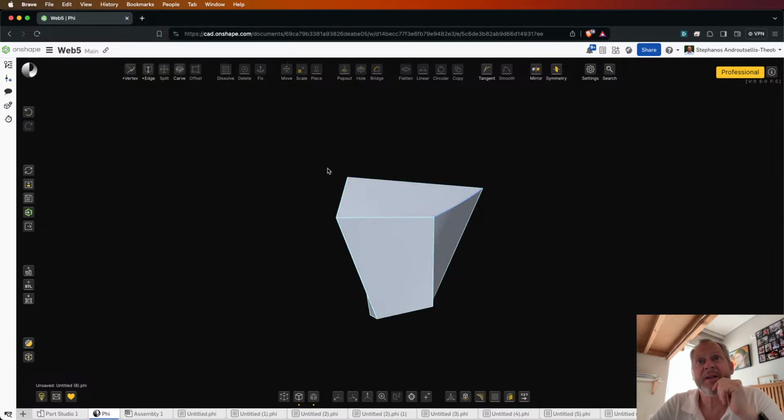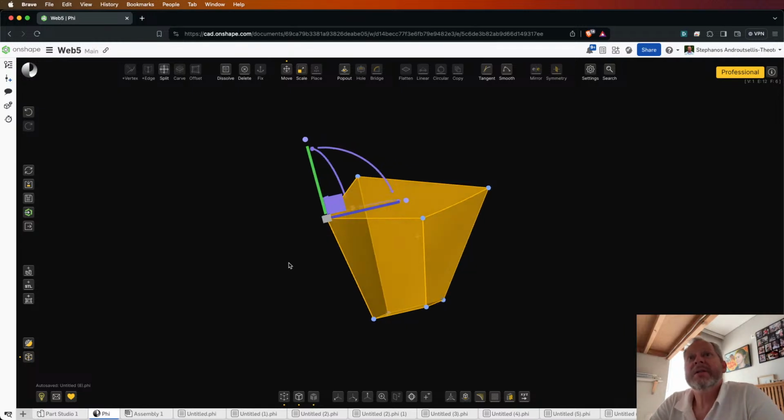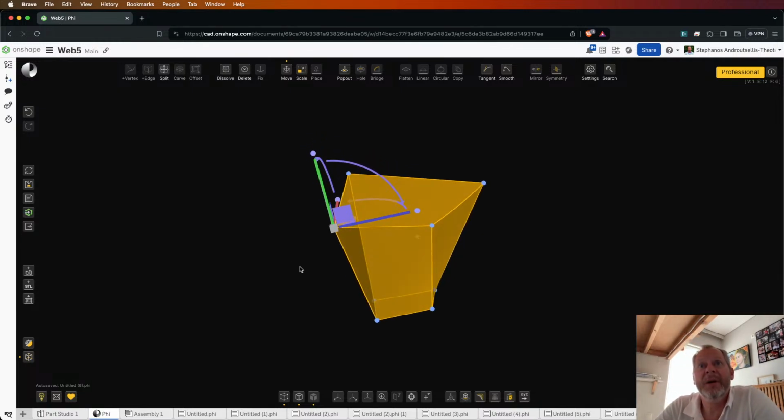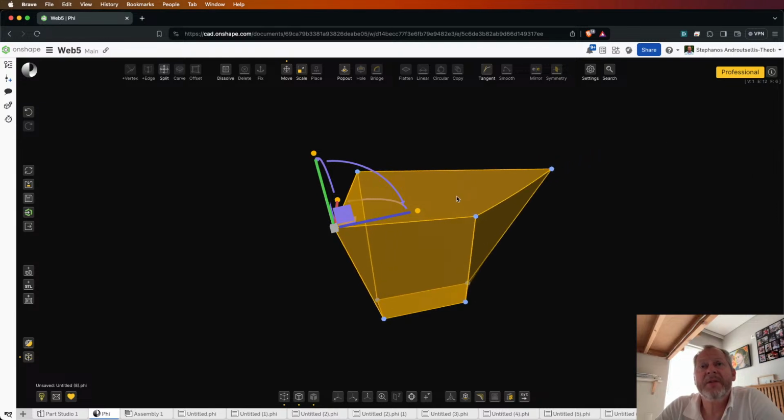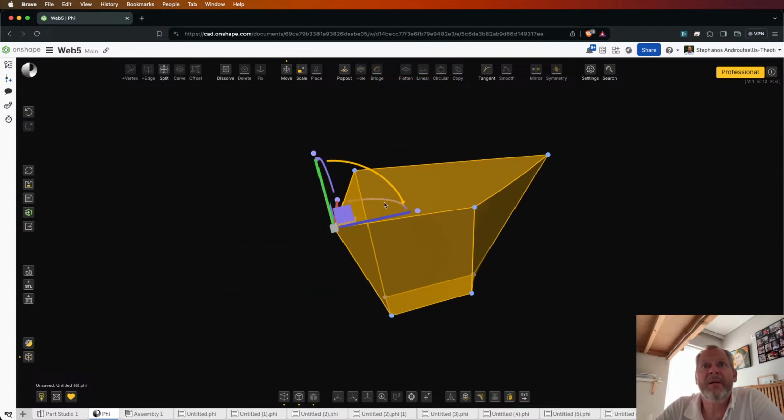If, however, I select my entire body and then I show my vertices and I select only one vertex and then hit M, then this is an indication that I want my manipulator to be placed exactly at that vertex. And this is very convenient because, for example, if I do a scale, like here, the scale happens around the position of the manipulator. So I'm scaling and keeping this point unmoved. Or if I'm rotating around that vertex.